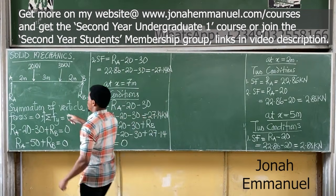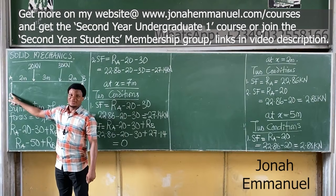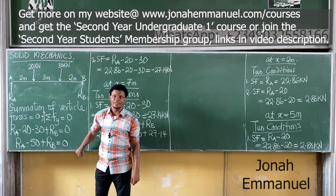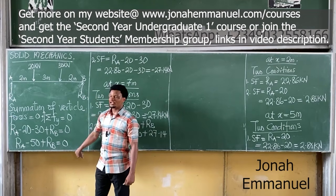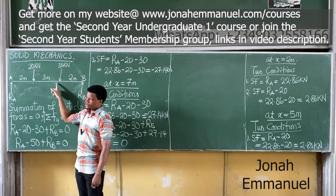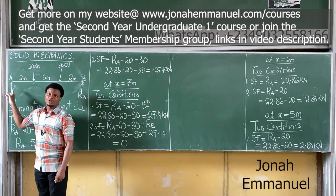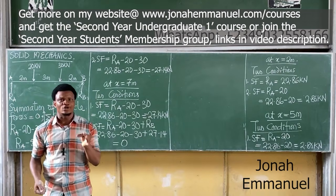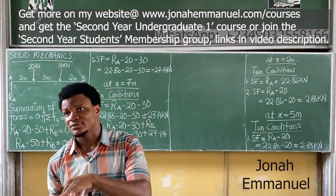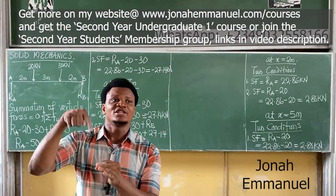You're asking why do you have 2 conditions for these ones, but not this one here? Good question. Listen, please. Why do we have 2 conditions at every point load like this one here? Look at this. We took 2 conditions, 2 conditions, 2 conditions. There was no 2 conditions here. Why? Simple. In the concept of 2 conditions, condition 1 is always what? All the forces before that point. Condition 2 is all the forces before that point plus the one at that point.